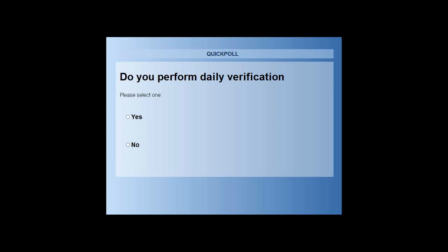And as we already know, an electrical safety test is only as good as the tester itself. A defective tester can lead to inaccurate or incorrect safety tests, giving false pass and fail results, which can lead to improperly tested products being out in the market, posing all kinds of electric shock hazards to the end users.